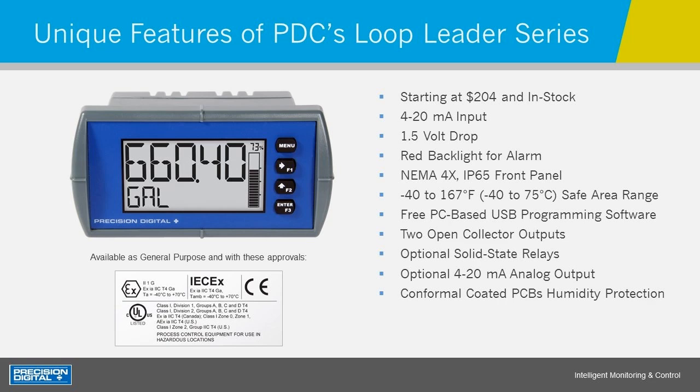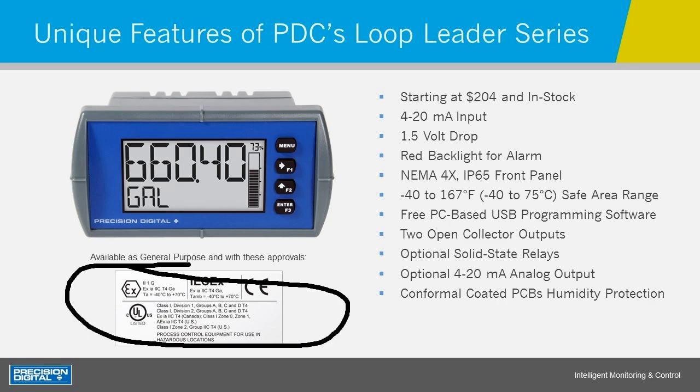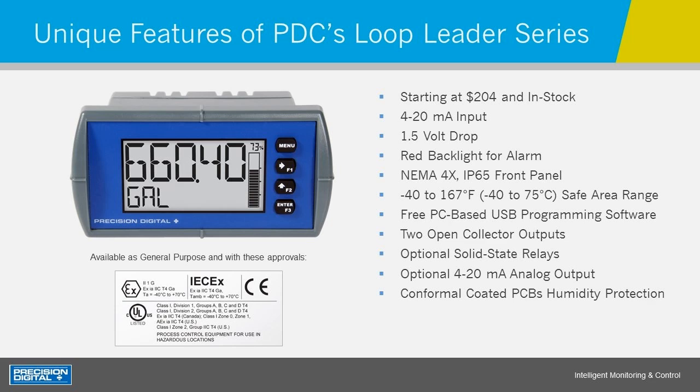Now, if you need something that's good for hazardous areas, these are, again, great Div 2 panel choices. And you can see here we've got ATEX and IECEx approvals, UL and cUL for Class 1 Div 1, Class 1 Div 2, because we're both intrinsically safe and non-incendive. If you're using us in that non-incendive panel, you can most likely wire us up without any barriers.